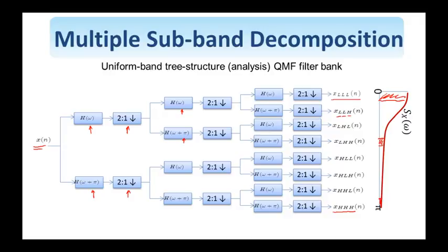So again, having one good pair of decomposition, I can cascade it this way, and I end up, in an equal rate as shown here, obtaining as many bands as I want in this multi-band decomposition system. And since this pair also has its perfect reconstruction pair, I can also go from this 8-band decomposition here, for example, to perfect reconstruction using the pairs that I started with.